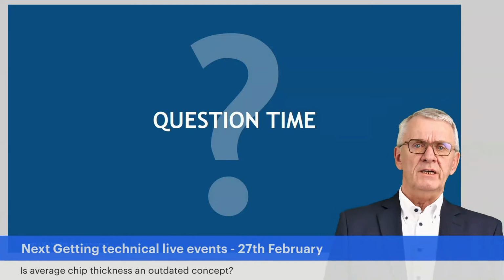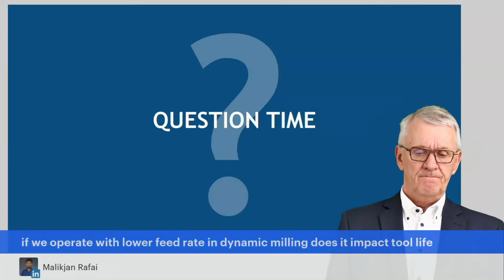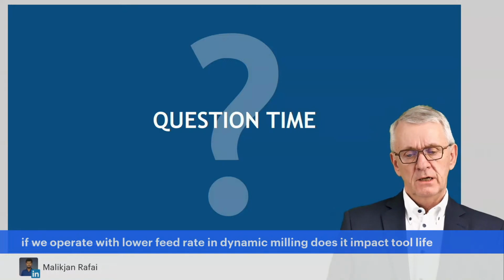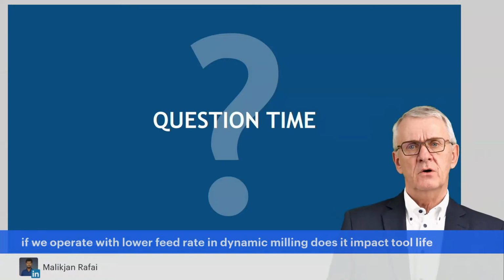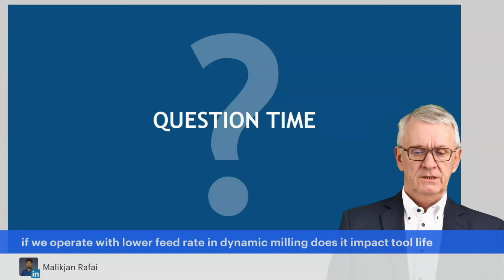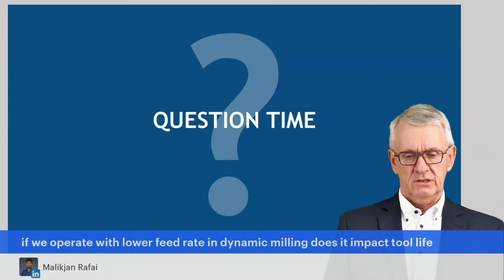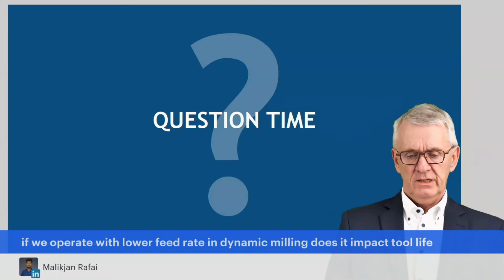If your feeds are too big, that's going to limit tool life. And that's due to mechanical phenomena. Overloading cutting edges, mechanical. If your feed is too little, you're also going to suffer from short tool life. But then it's not mechanical overload, then it's thermal overload, kind of. So yes, but I should explain more, see next session. But I think this is a truly very good question.